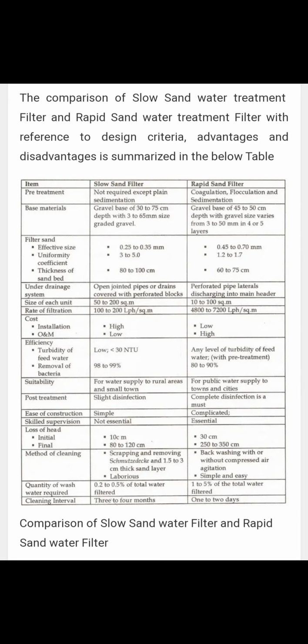In this coagulation process, we add alum and lime as coagulants, so that the suspended, colloidal and dissolved solids come closer and create sizable and settleable flocs, and that heavy floc settles down easily at the bottom of the tank. That is the process of the formation of flocs, and the process is called flocculation. For completely mixing the coagulant, we use the clariflocculator, and that process is called clarification. So this is about sedimentation with coagulation, flocculation, and clarification.